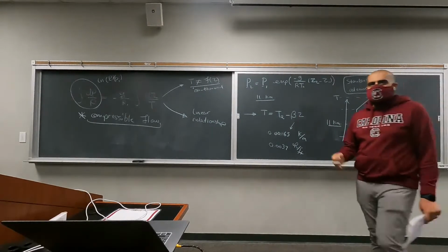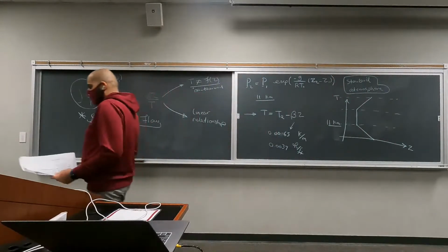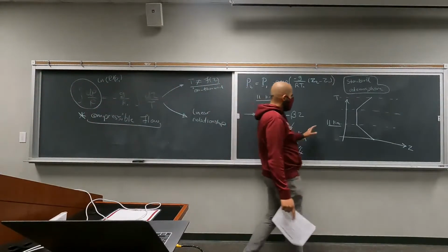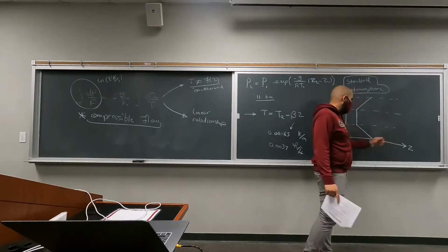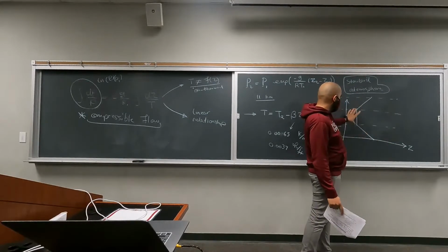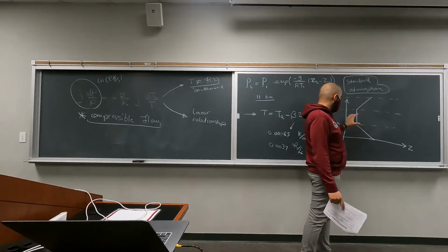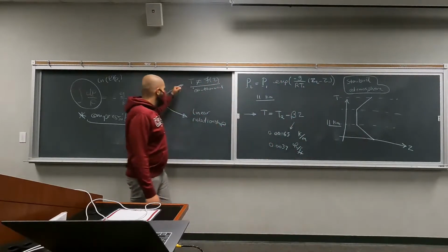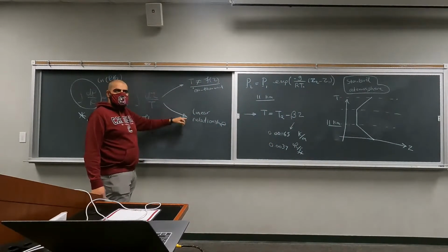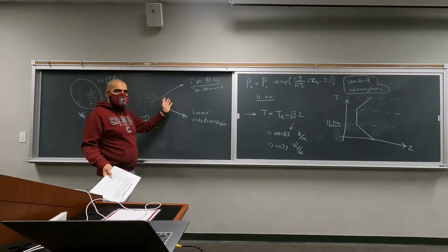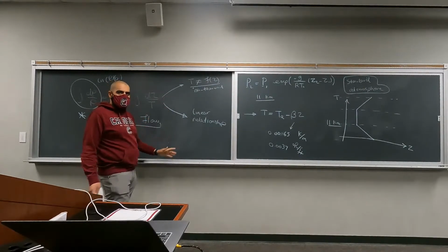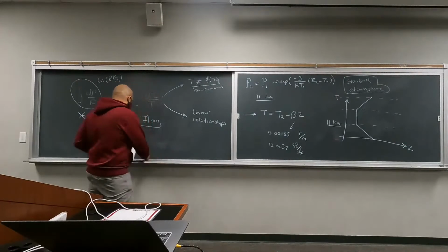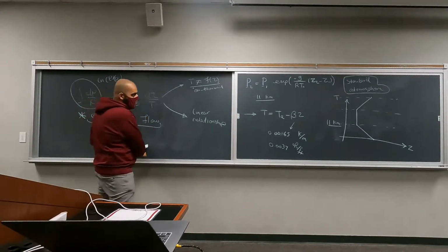The point is, using this standard atmosphere standardization method, we are essentially finding the relationship between temperature and Z, and we see it is constructed of different relationships, but all of them are isothermal or a linear relationship. So these two solutions work for us. We don't need to make things more complicated, right? We don't need to find complex, like polynomial relationships between temperature and the altitude. Does this make sense? Okay.